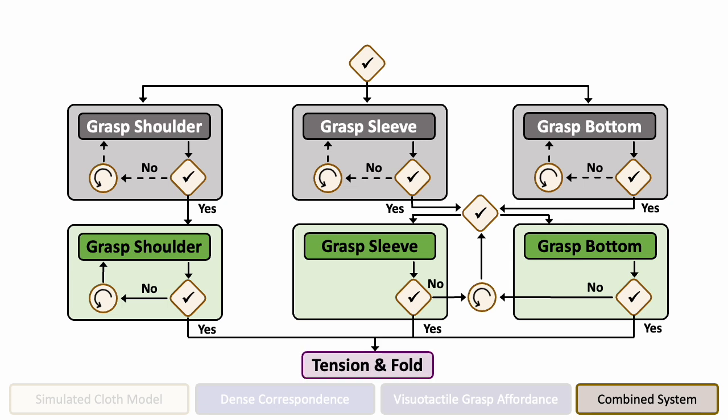If we can't find a good grasp at any stage, or if the cloth slips, we can return to a fallback option and start over. If we can't find a good table grasp, we just grasp the highest point. If we can't find a good grasp in air after rotating a full rotation, we grasp the lowest graspable point to help unfurl the cloth.